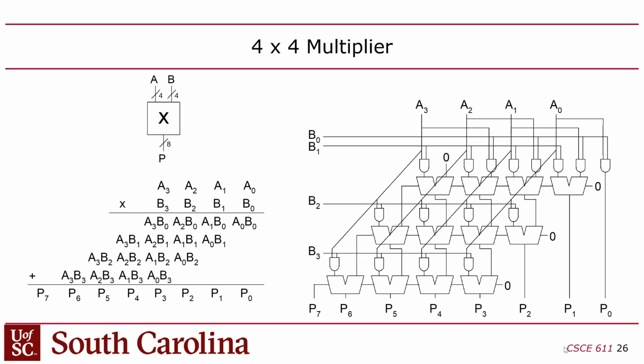That makes sense? So in order for this to work, you have a 4-bit multiplier, two 4-bit operands, and you're getting an 8-bit product. But the propagation delay here would be going through four adds, right? But that only requires actually 3 adders, because there's only 3 layers of adders here, even though it's 4 bits.